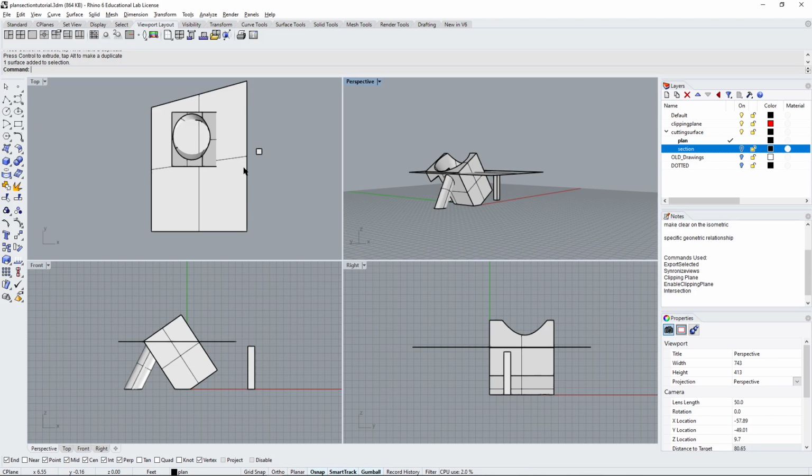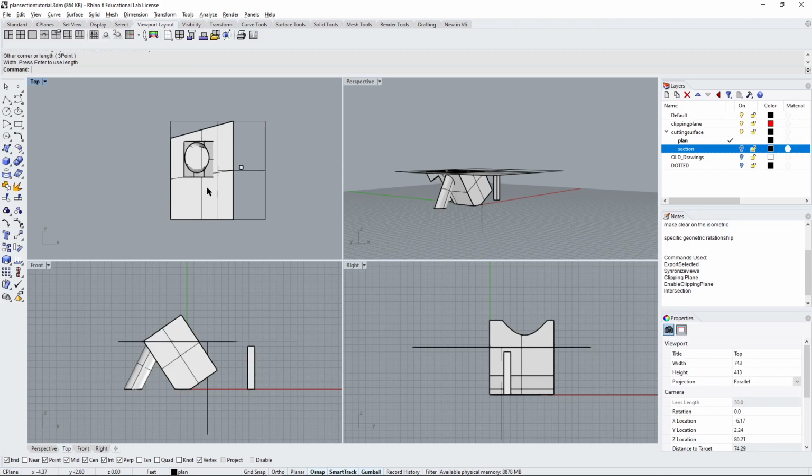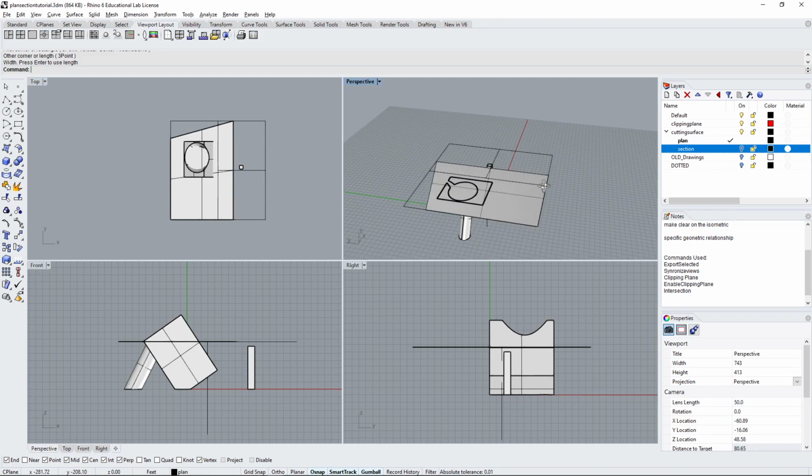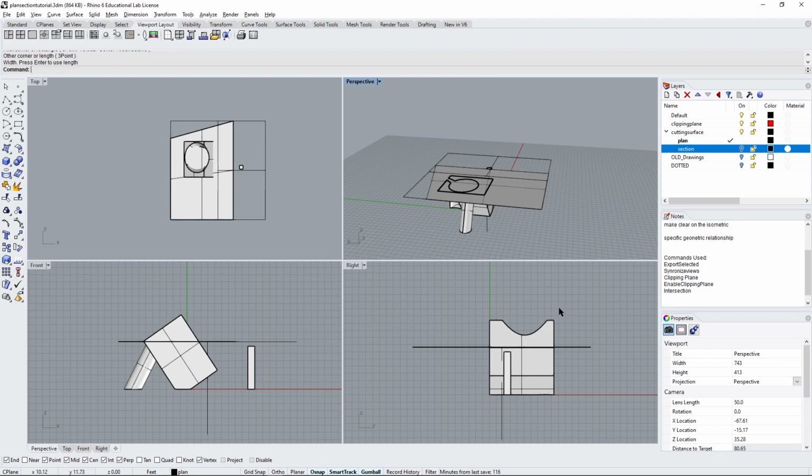We're just going to use the command clipping plane. So we enter clipping plane. You'll see just like when we use planar surface, it asks us to pick the parameters of our plane. Pick the corners, one here, and we can check because we've got the synchronized viewport. We can see exactly what's going on. Right here, you can see that it's picking the surface just like I want it. So this is great. So what it's done is it's cut off the top of my shape in my view. So why can I see the, can't see the top here, but I can see the top here.